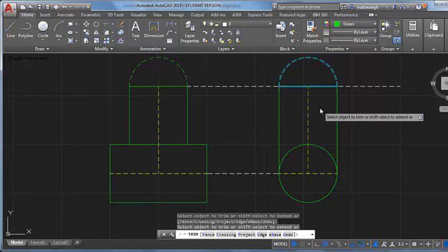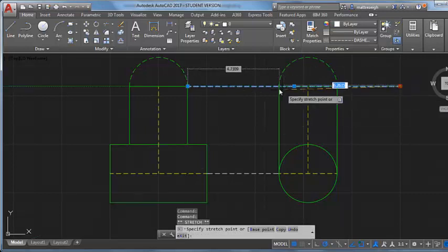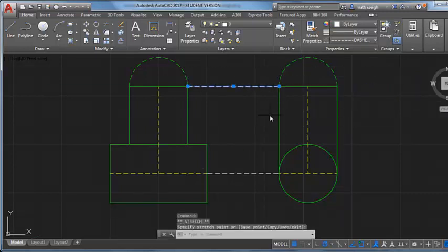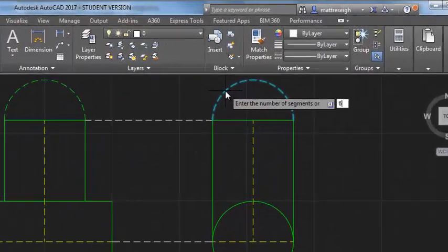Get rid of that. This is a projection line, so I'm going to just keep it clean and tuck it back to where that's as far as it would really need to come over to define my overall height. I need to divide this circle the same way we've been dividing. So I'm going to do that one by my 6 lines.